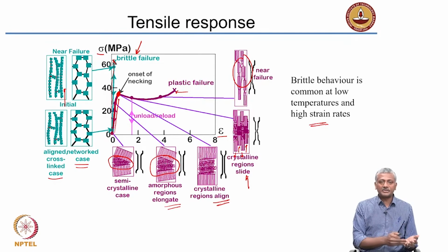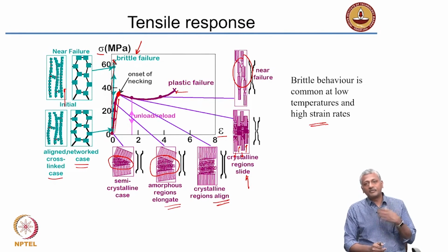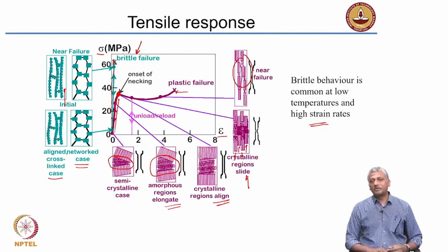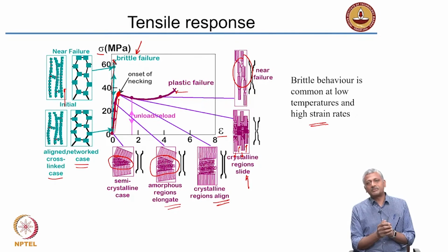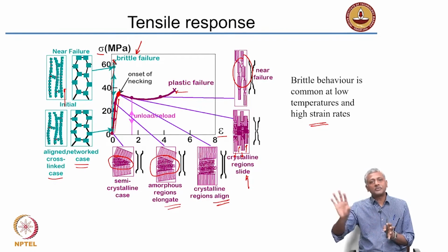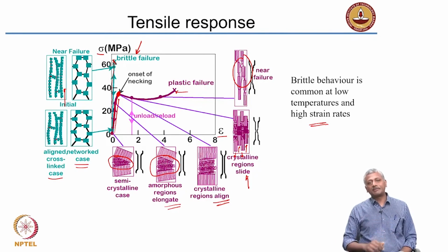When you go to negative temperatures, the behavior of asphalt will become very different. It will have low temperature thermal cracking, or brittleness will be introduced, and there will be cracking in the pavement because of the cracking of the polymer, that is the bitumen. Okay. So, all these have practical connotations. Whatever you learn in the basic understanding of construction materials will have connotations to how these materials actually behave in real life applications.